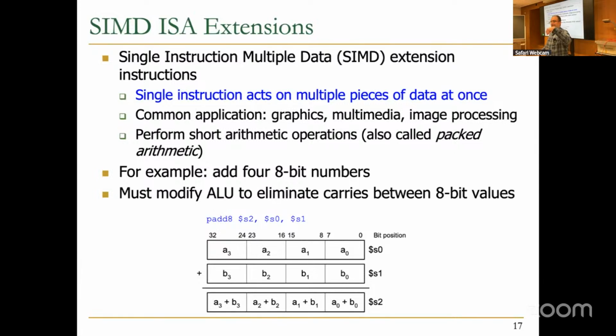You just encode the first 8 in 4 bits and the 9 also in 4 bits. And when you want to do operations on these encodings, you also need such support. You don't necessarily need to propagate carries, for example, or you may need to propagate carry in a different way. So people have been doing that a lot. And I think that kind of experience also helps people to build quickly on such stuff as well.